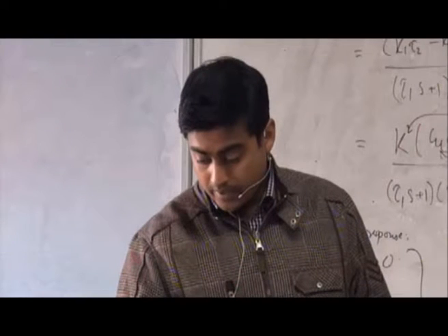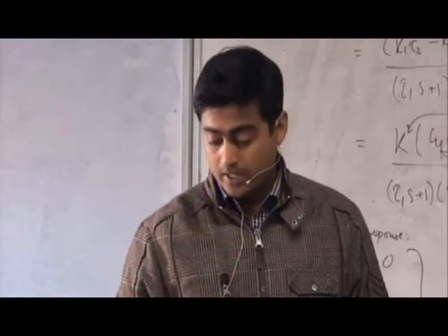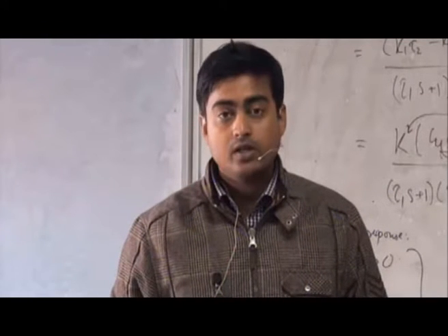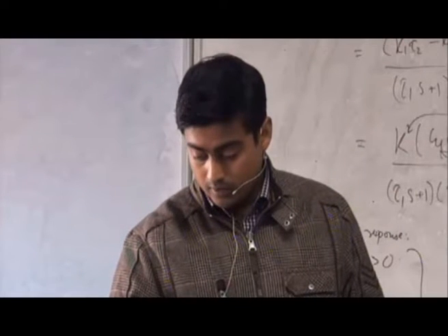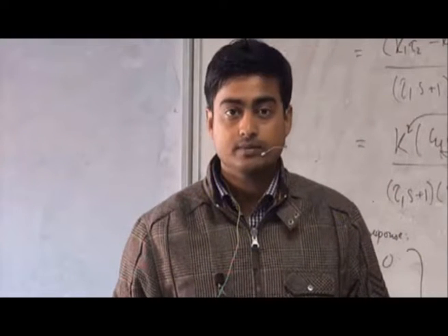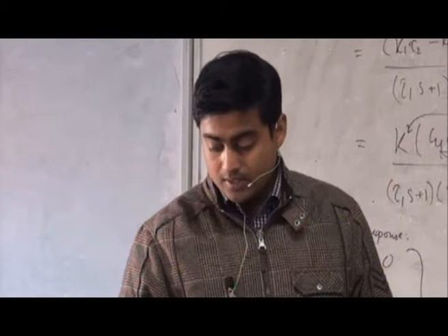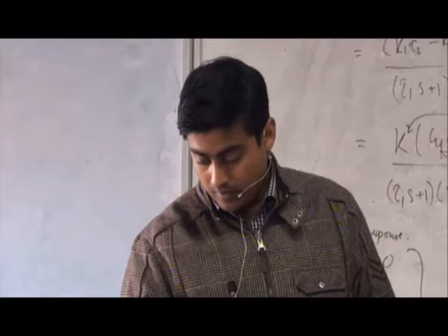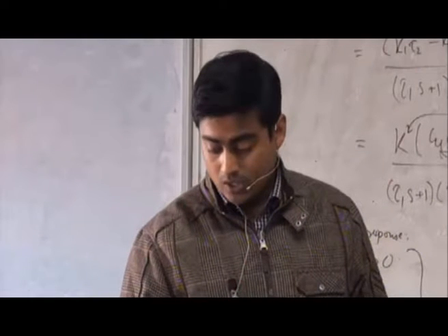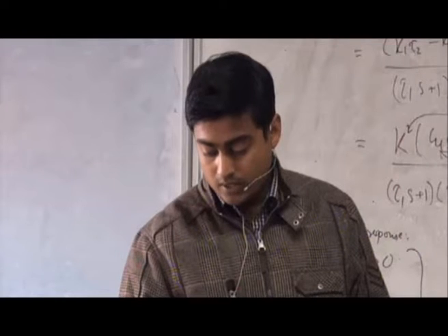Okay, and the red one is the control variable which you manipulate so that the liquid level in the boiler could stay at the set point value. And the blue one is basically the measurement, the output. Okay, since the system is in operation, if you give a constant u from here to here, or whatever the controller has been designed, the measurement was actually following the set point.